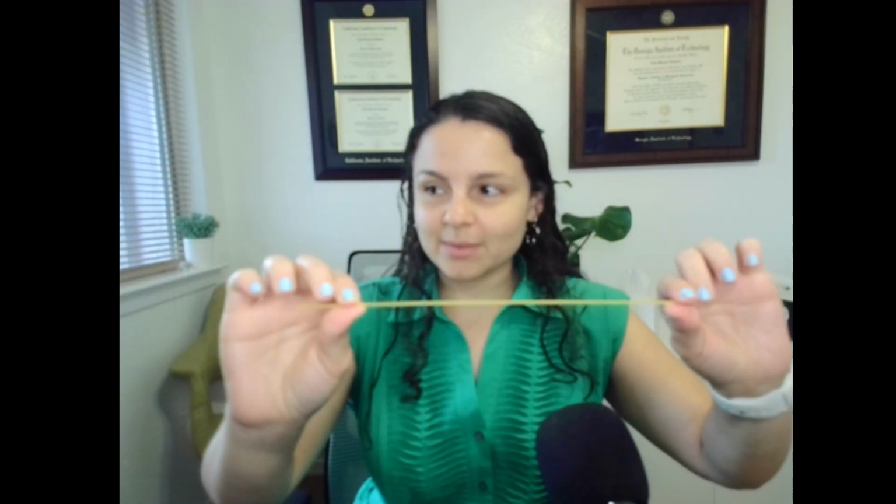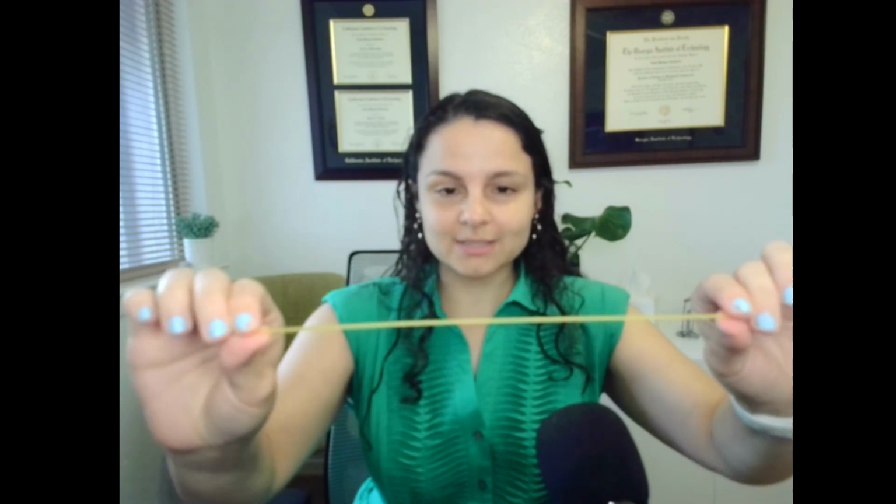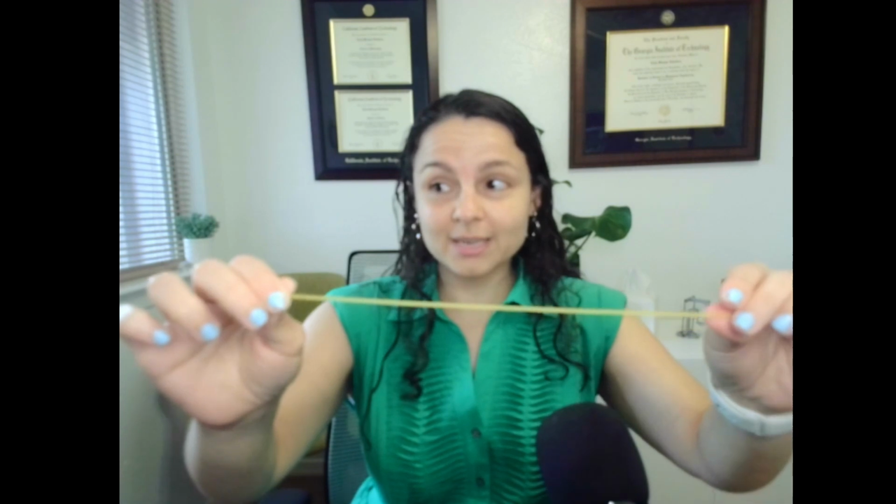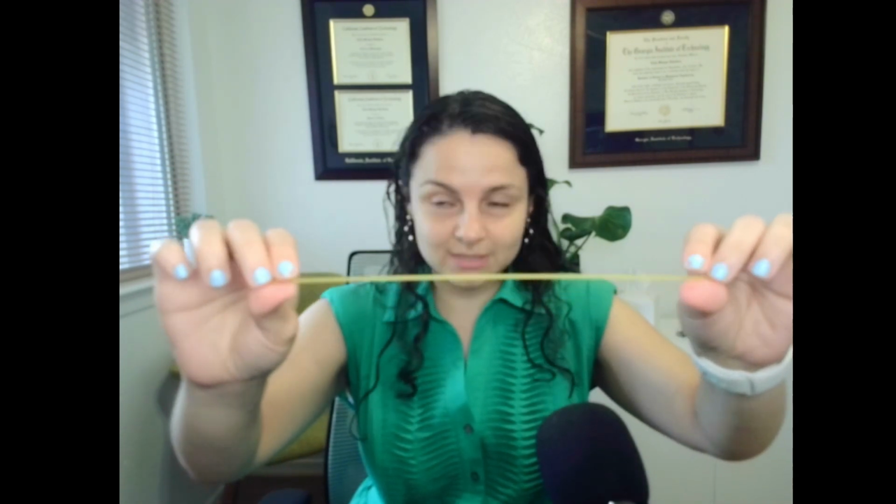Now, here is a brittle material, which is a piece of dry spaghetti. Let's apply the same idea. Let me bend this until we get some failure. You can see that I can get it to bend. If I let go, it's going to return exactly back to its original state, right? So we're not getting permanent deformation. We're getting deformation, but it's all elastic. And if I keep going, it broke into a few pieces, just sudden fracture, right?